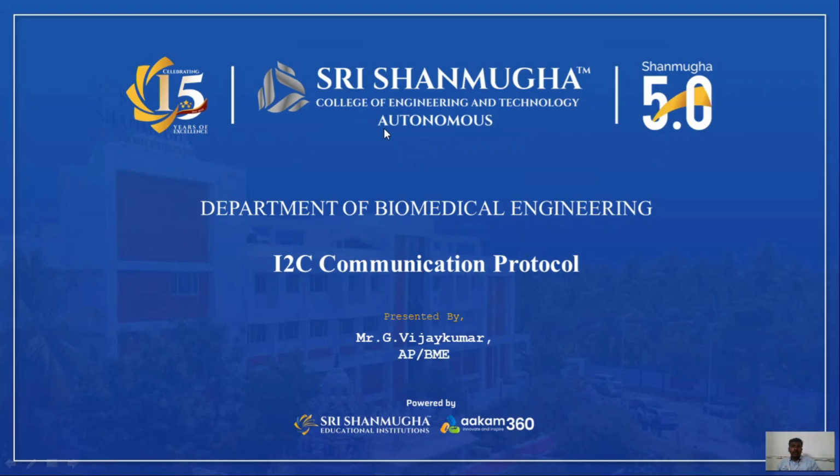I2C, which stands for Inter-Integrated Circuit, is one of the most important communication protocols used in embedded systems, microcontroller based systems, biomedical instruments and IoT devices. Wherever we need a microcontroller to communicate with sensors, displays, memory devices or real-time clock modules, I2C is often the preferred communication method because it requires only two wires and supports multiple devices on the same bus.